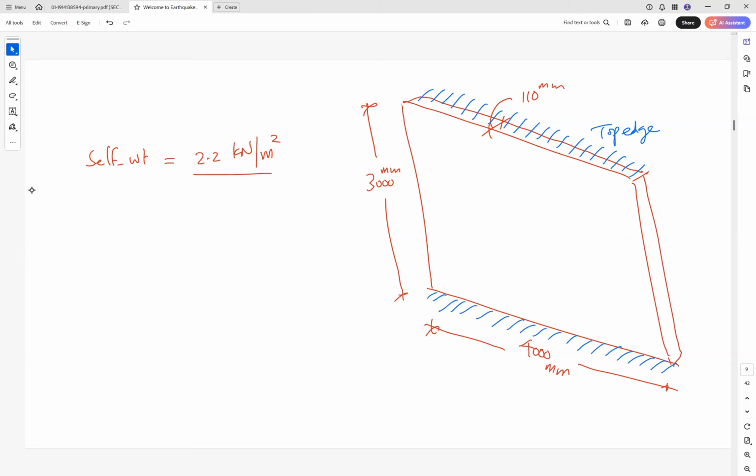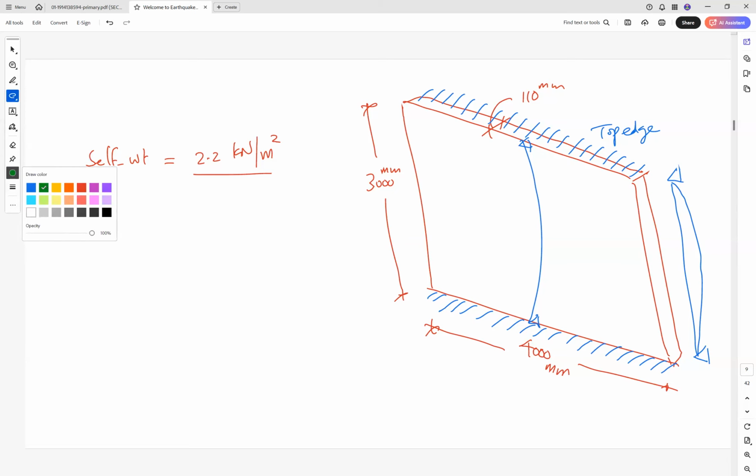So this wall is susceptible to bending, vertical bending or horizontal bending, similar to what we were explaining. Because we have one support at the top here and one support at the bottom here, we have only one way vertical bending. So the wall is subject to one way vertical bending, and the wall will crack or break at the mid height somewhere. So this is what we expect.